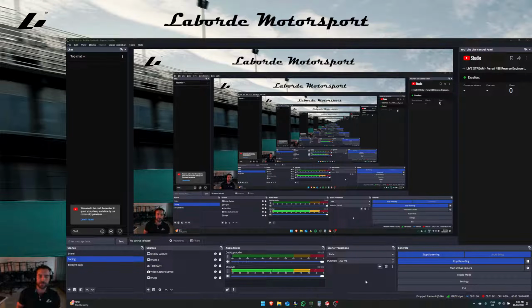WinOLS is something that I use every day and is a very big part of the reverse engineering process. A lot of people will use something like Microsoft Visual Studio or Visual Studio Code with the HighTec IDE compiler, which allows people to compile C++ into Tricore assembly language, and then they can inject their code that way. For us, we're going to be doing it with Ghidra.